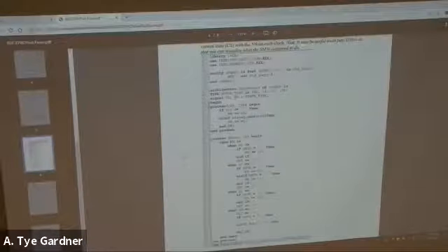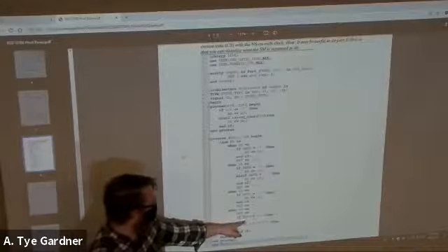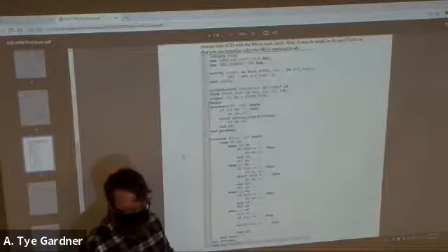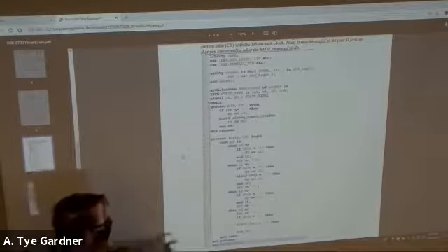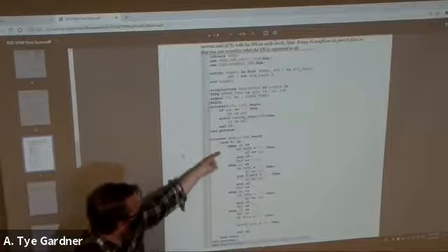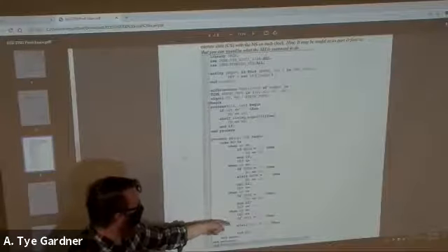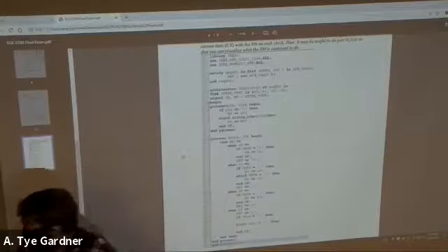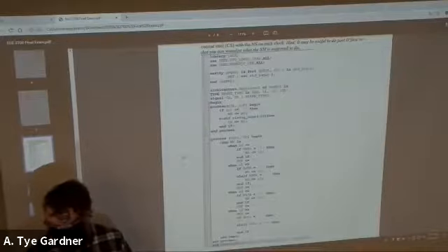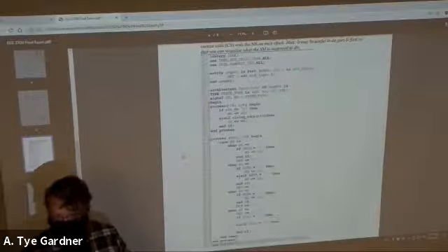But for now, let's look at it. What does state 3 do? Well, state 3 is just saying if we get a, oops, I didn't finish this, right? If I see a 1, go to B. If I see a 0, go to C. So it should say if data is 1, go to state B, so we would say next state equals S1. Else if data is 0, next state equals C, which is S2. That, right? Nice and easy, I hope.